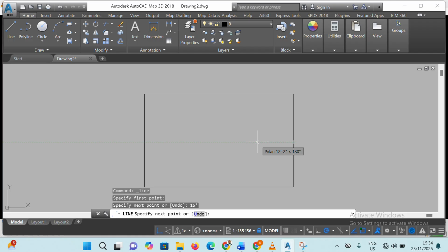Then you move your hand along this direction, that is 15 by 12 feet. You enter 12 feet, you press enter. You can enclose by clicking on this, and then you press escape. Then you continue the demarcation block again by clicking line. Then you continue along the straight line, and you are leaving a space according to the design, the selected plan of 6 inches, and then you press enter.